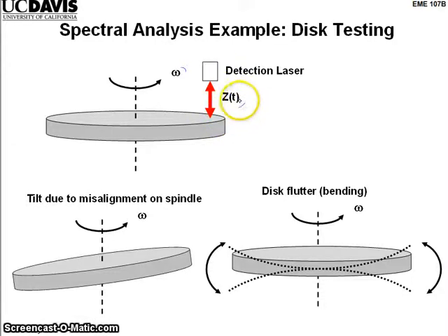But in reality, there are always going to be some imperfections. One thing that can happen is that the disk may be misaligned to the rotation axis. When you clamp it on the shaft, there are always little imperfections in that clamp, so the disk is never perfectly flat.